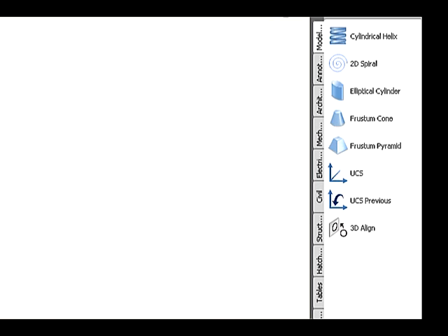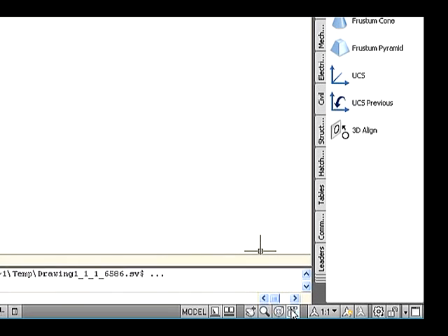Show Motion. If you do presentations for your clients, then you will love the new Show Motion feature. Show Motion tools let you quickly step through different views in your drawing, with different effects, for presentation purposes. The feature can be found on the status bar or by executing the Motion command. Annotation options are similar to the previous versions of AutoCAD, so let's see the other options of AutoCAD 2009.